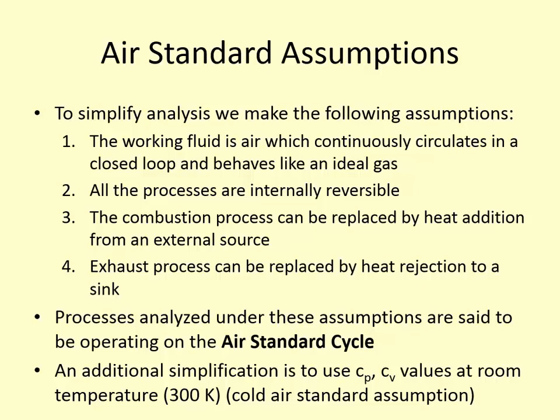The combustion process itself, we say, is just like a heat addition process. And then the exhaust process, we say, is like heat removal. So we're exhausting hot gases, and we're saying that's like heat is being removed from the system. And the combustion process itself is like heat is being added, rather than needing to know the chemistry involved. So if we're undergoing a process that relies on these four assumptions, it's said to be operating on the air standard cycle.